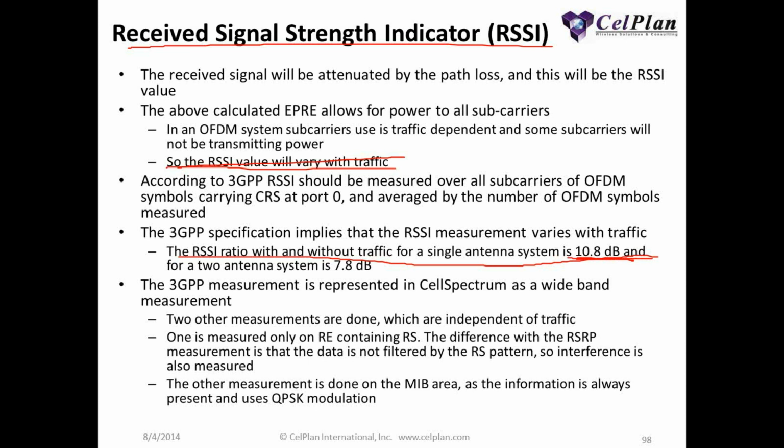3GPP specifies a wideband measurement. It should be measured across the whole band and then expressed in terms of one resource block. Also, excuse me, it is for the whole band, not of all resource blocks.